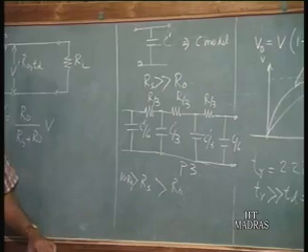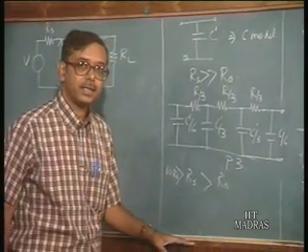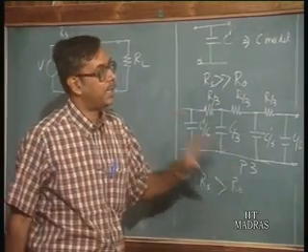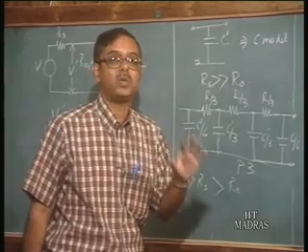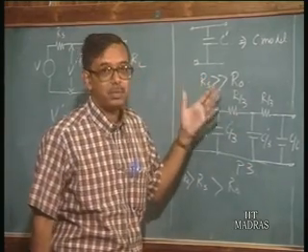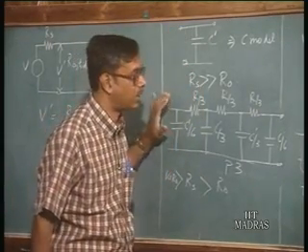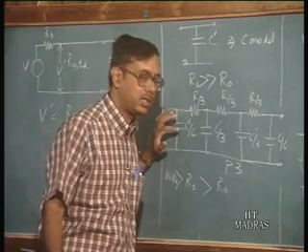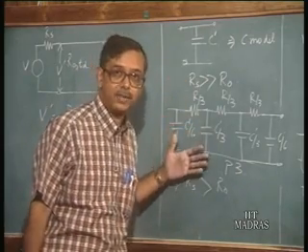for this situation. When the source resistance becomes less than the characteristic resistance, we have to go for transmission line analysis. In fact, we must remember that the transmission line analysis is always correct. It always gives the best results, but in many cases it may not be necessary to go into the transmission line analysis. We can use these simple models to get results which are similar to the transmission line results, with much less computation time. So that is the advantage.